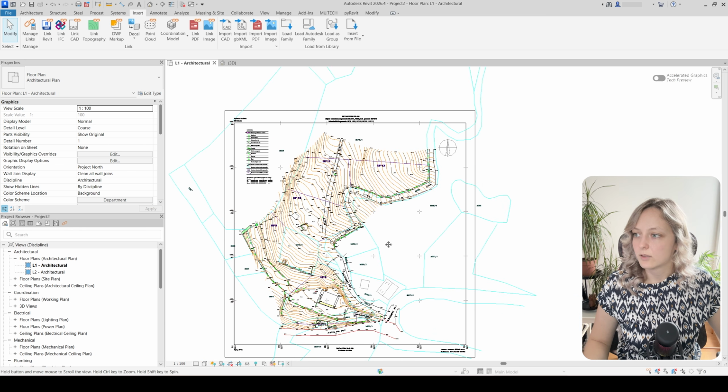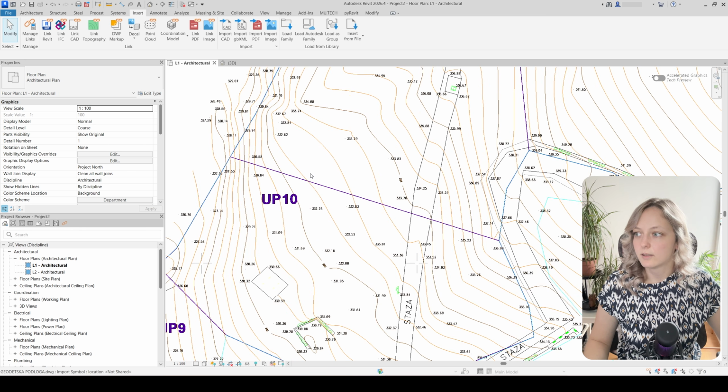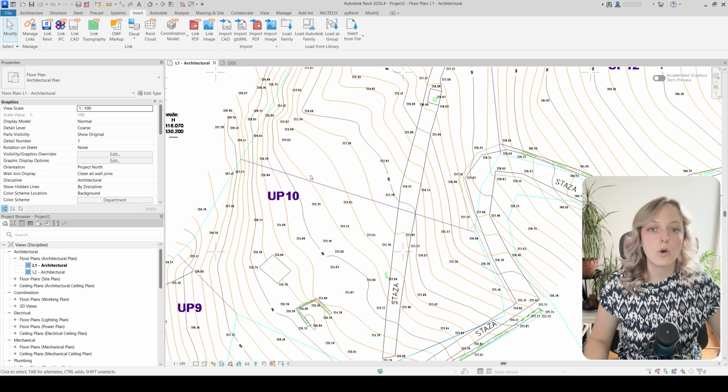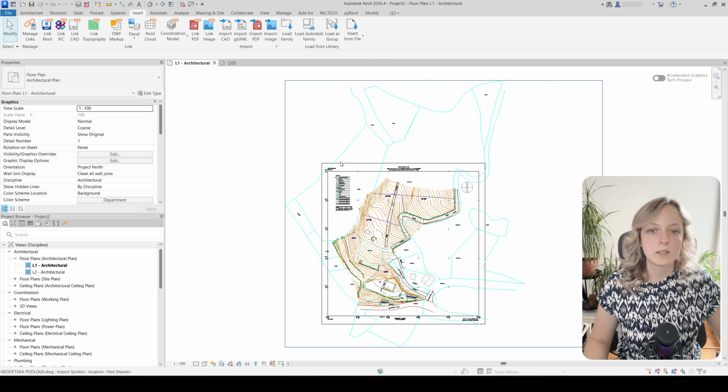As you can see, this file is very clean, lines are very nice, they are no longer squiggly, and I no longer get the notification that there is a faraway geometry. I can also do the zoom extends easily, and this way I have cleaned my file and made it ready for being inserted in Revit.